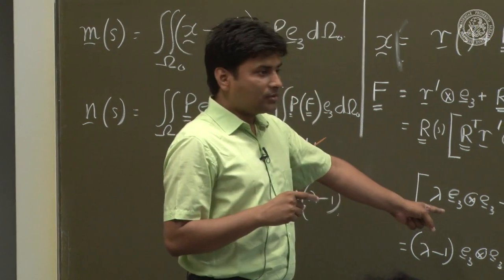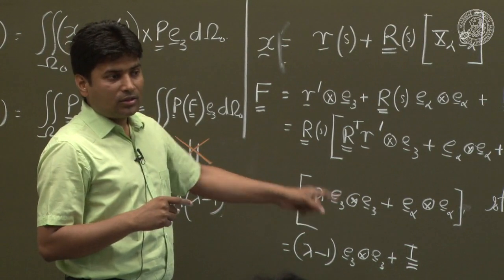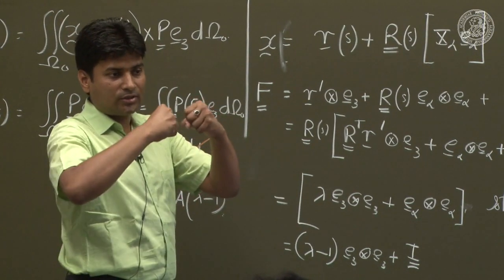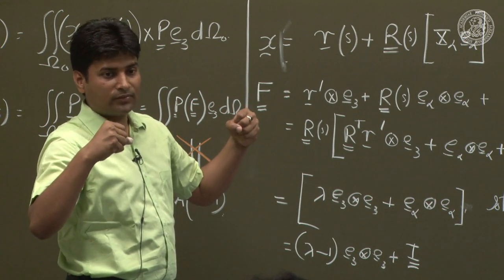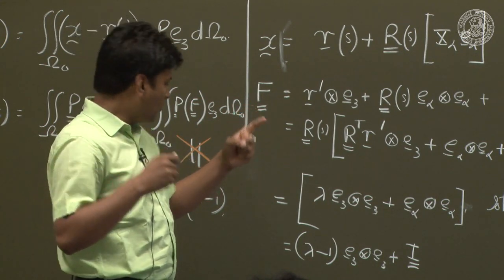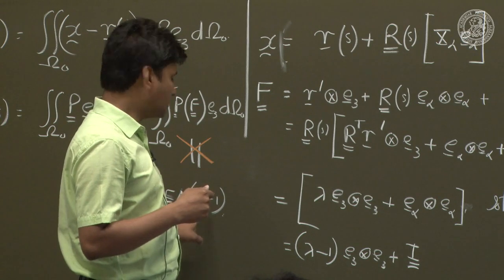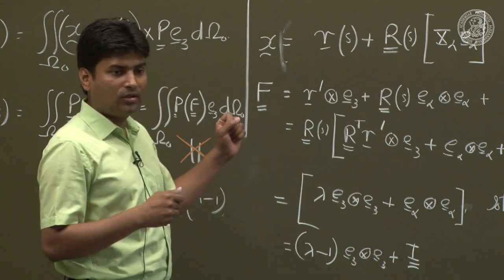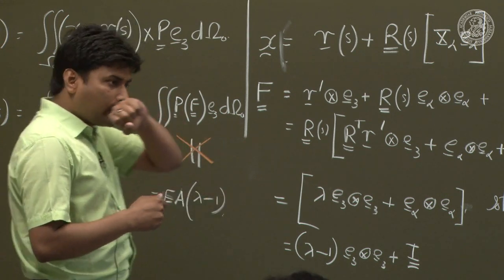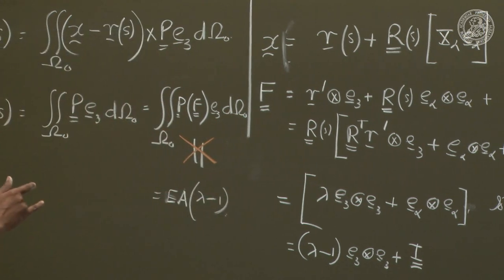See, this kinematics is not allowing the cross section to shrink as you are stretching it. So you are making your system stiff. Therefore, the modulus term does not turn out to be this, it will turn out to be higher than this number, EA.